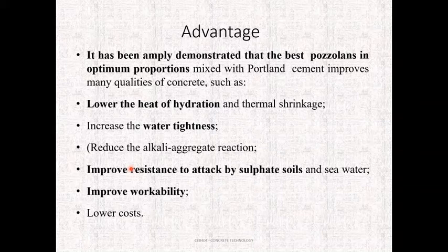Advantages of using the mineral admixtures. It lowers the rate of hydration and thermal shrinkages. It increases water tightness. It reduces alkali aggregate reactions. It also improves the workability and lowers the cost of the concrete.